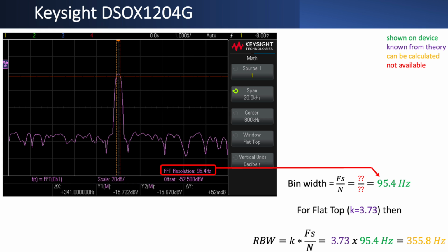If we go all the way back to the upper menu in the hierarchy, we see a sample rate, but that is clearly the overall sample rate and not the decimated sample rate that goes into the FFT calculation. And the number of FFT points, which is a maximum of 64K for this oscilloscope, the actual number used in a particular situation or calculation is not shown either. So we're kind of left in the dark exactly what this bandwidth is based upon, but it is being displayed.